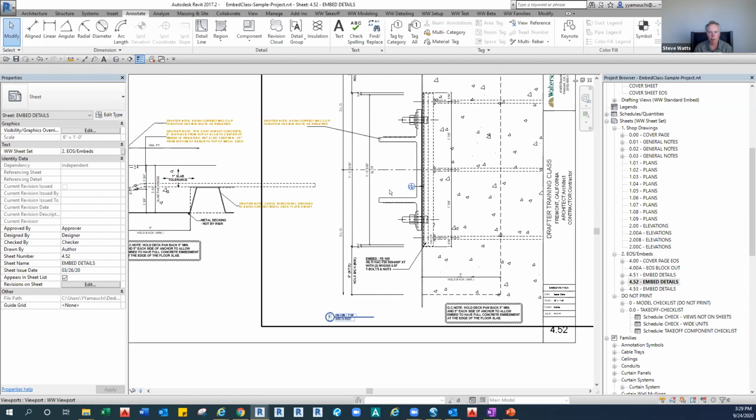But in Northern California, we definitely typically install the embeds, because DevCon likes us to do that, Level 10 likes us to do that. There's a few GCs that don't. But again, typically we're not putting that embed on until after the concrete is poured, because we don't know the deck level. Yes. So I don't think they're going back with it, they would use that embed plan, telling them which mat clip to put where.